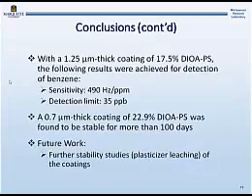using 1 single pair of plasticizer and polymer, we observed the highest sensitivity and lowest detection limit for our coating, which was 1.25 micrometer thick and the mixing ratio was 17.5%. The detection limit has actually been measured, so we made many measurements below 100 ppb concentration for benzene. And by increasing the mixing ratio and decreasing the thickness, we slightly lose some sensitivity, but we get stability for more than 100 days.